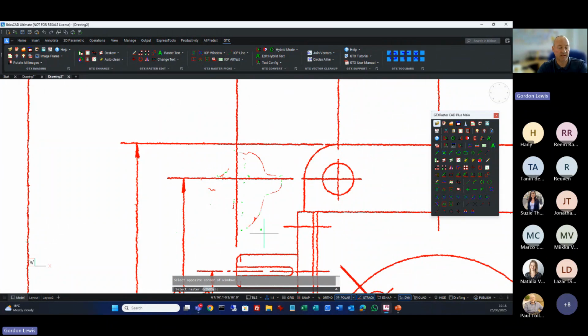It's all associated together, so we have a command called erase. If I use a selection method called inside, and then draw a window exactly the same as before, it will see the data that's all on its own in that window, highlight it, and then I can get rid of it. It's left all the geometry behind because it was going in and out of the box and was joined up. So it just picked the data that was all on its own.